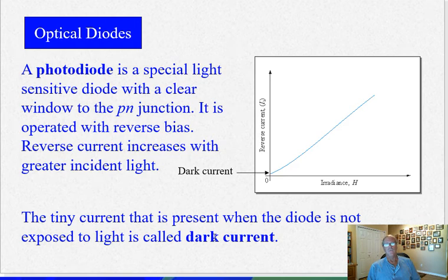Now that's LEDs. Now photodiodes work the other way. In other words, it doesn't emit light; it takes light in, and it's an exposed junction. And whenever you have an exposed junction, you bombard it with photons. What that does is it changes the depletion region and will change the amount of current that is able to pass through the diode in reverse bias. Again, these are reverse bias.